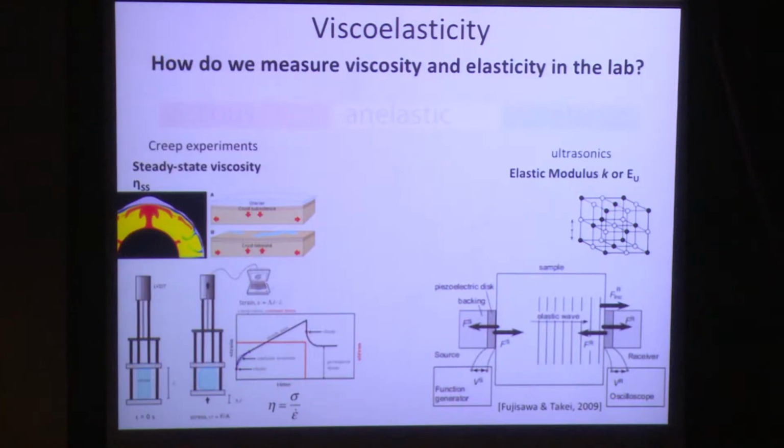The way you would measure those two end member properties would be, there's lots of ways to measure elastic properties. One good, non-destructive means is to use ultrasonic waves. You can send a P wave and an S wave, and from that calculate your various elastic moduli.